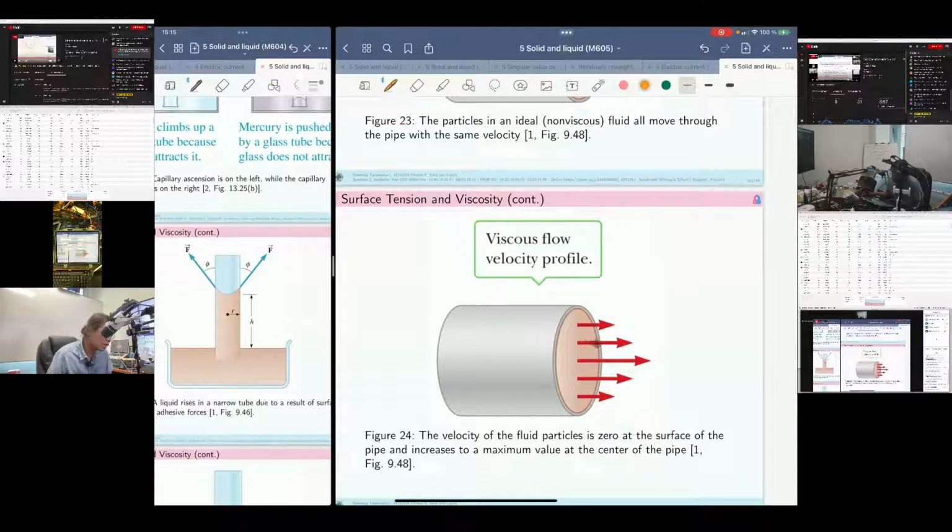And among several layers of fluid, there is friction, but it's not so strong as the friction between the fluid and the internal wall of the pipe. So there is high friction here, there is low friction here. With the low friction, the fluid can move easily. So the easy movement means the high speed or high velocity of the fluid flow here.